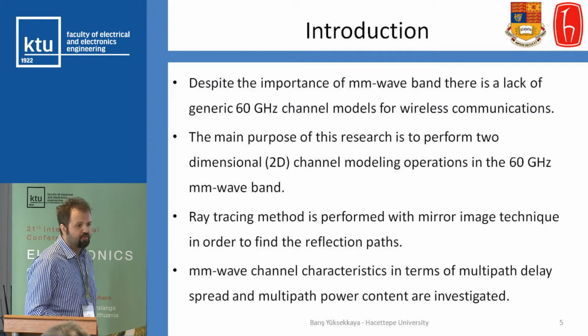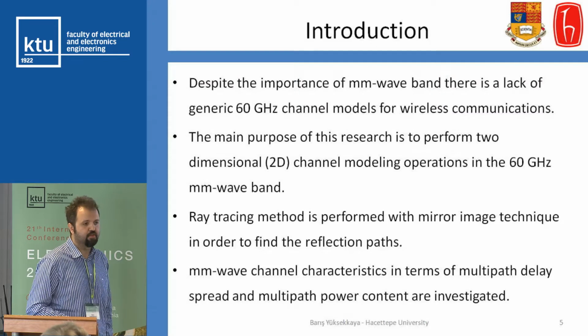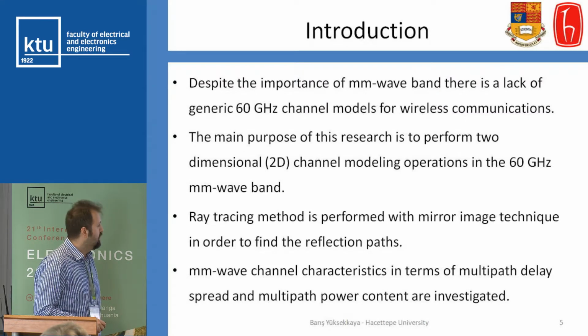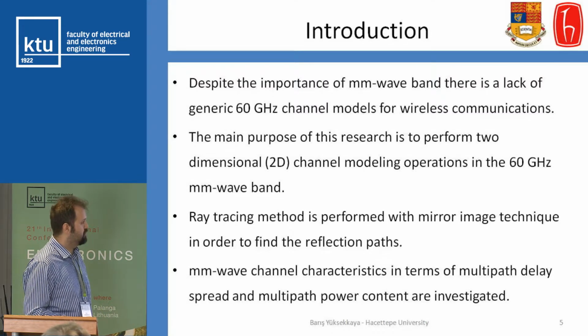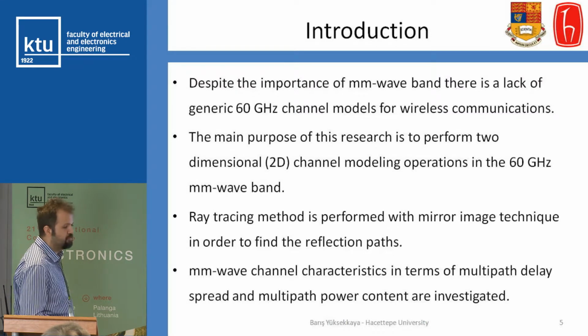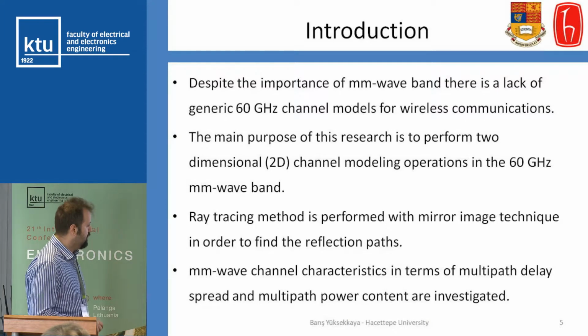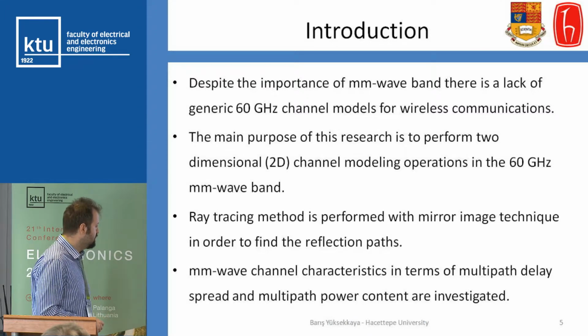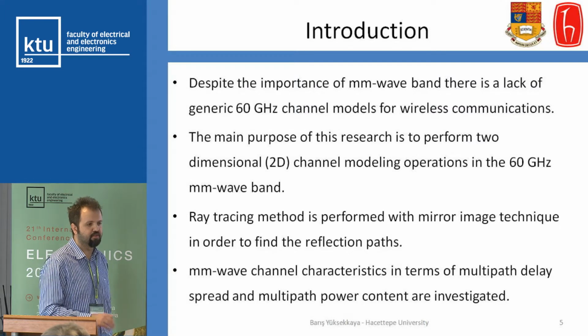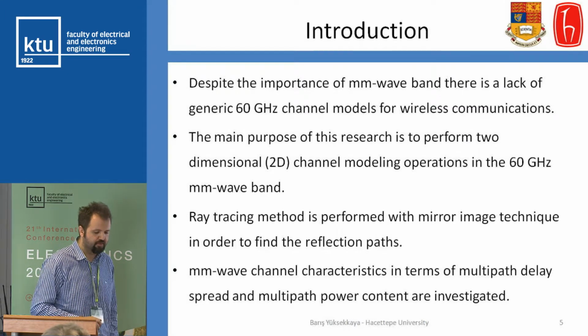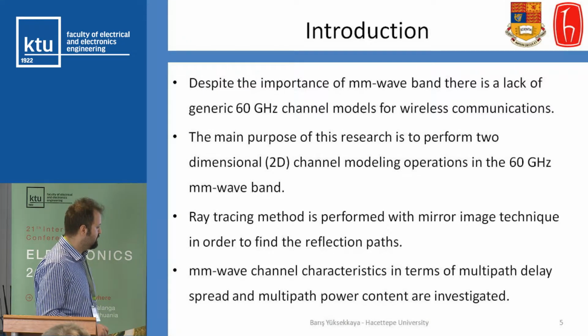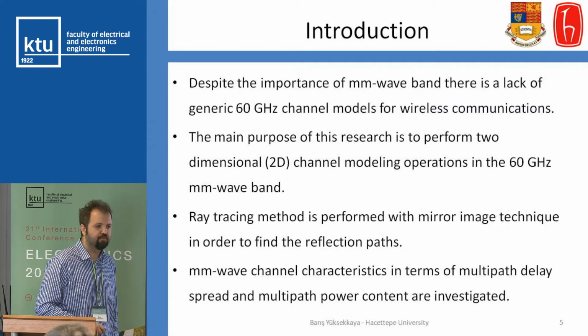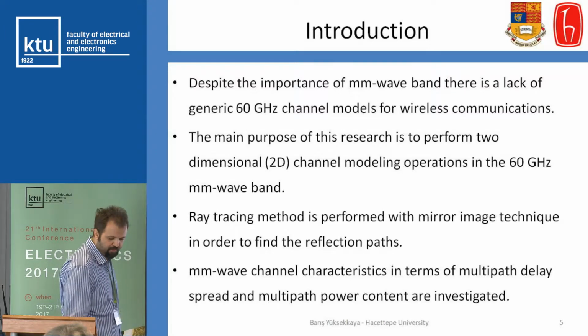Despite the importance of millimeter wave, there is a lack of generic 60 GHz channel models for wireless channels. The main purpose of my research is to perform two-dimensional channel modeling operations in the 60 GHz millimeter wave band. I have used ray tracing with the mirror image technique in order to find the reflection paths, in order to find the multiple paths of the channel. And I have investigated the characteristics in terms of multipath delay spread and multipath power content.